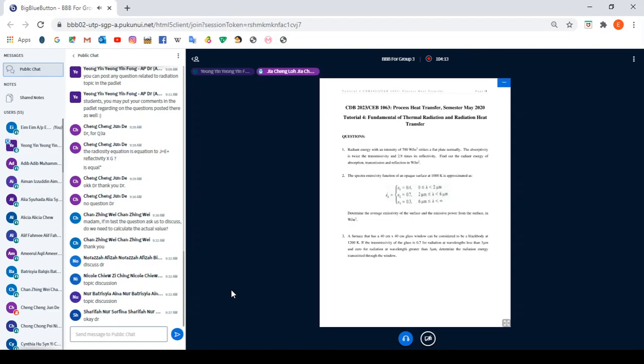Doctor, for internal forced convection, we are not using LH, right? Yeah, we are using LT. For turbulent flow, LT and LH are the same. And for turbulent flow, LH and LT equal 10D, right? Yes, correct. Okay, thank you.